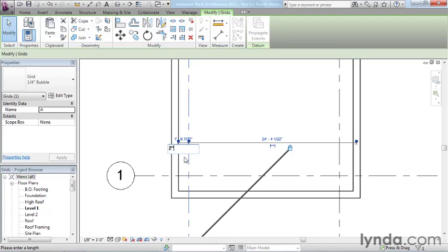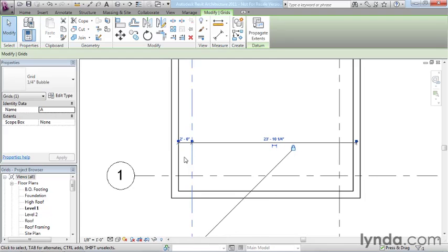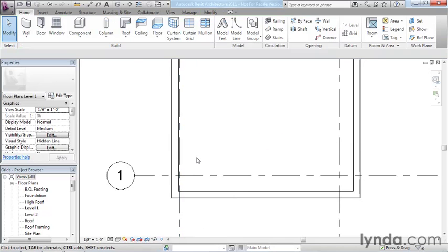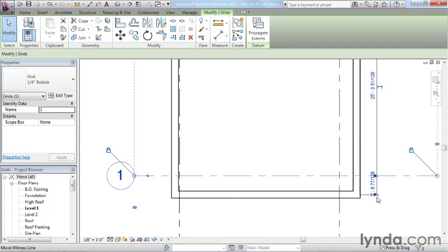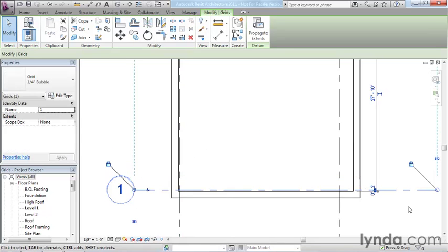Now in Revit Architecture, feet is the default unit. So if I just type 2 and press Enter, Revit's going to see that as 2 feet. So if I want 2 inches, I need to type 2 inches. I have to use the key right next to the Enter key with Shift held down, the little double apostrophe. Okay, that's the inch symbol, and that will give me 2 inches. So very important that you remember that. Again, not a big deal if you do it by mistake. You can just edit it again, but it can get frustrating if you put in feet instead of inches continually. So try and get in the habit of remembering to type inches when you want inches.